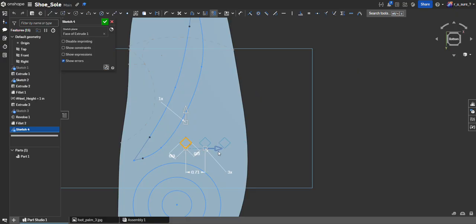And then we'll see a bunch of these symbols. So this one right here is the distance between, is the actual dimension of our square, and then this one is how many times you want it in this direction. So I'll say maybe 4. I want 4 layers. And how many do you want in this direction? I want to keep it at 3. And you can use this right here to start to move it around. And you can use this to spread it out.